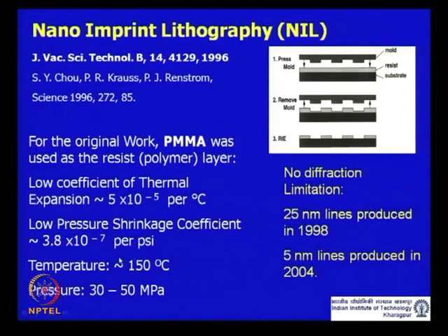Typical temperatures vary from 150 degrees to, let us say, 200 degrees centigrade, depending on the molecular weight. The glass transition temperature of PMMA is around 115 to 125 degrees centigrade. With the back of the envelope, you may remember that we are talking about polymers.